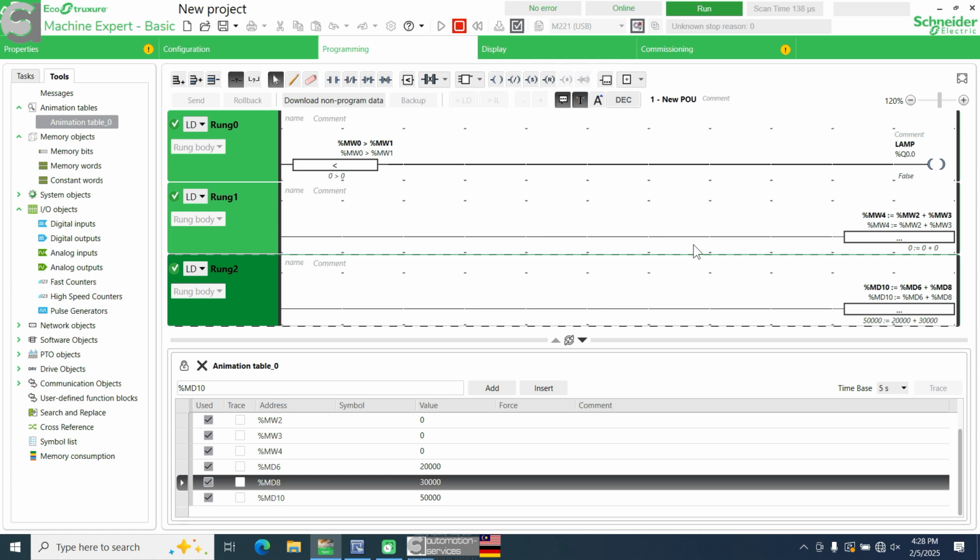So who is controlling increase and decrease of the temperature? The heating coil. The heating coil is just on and off only. So you will have a digital output connected to your heating coil. So it is not necessarily that the output must be analog output. The reading is the numbers. Okay, let's say you put 80 degrees, but currently inside here is 40 degrees only. So how does the PLC know it is 40 degrees from the analog input?